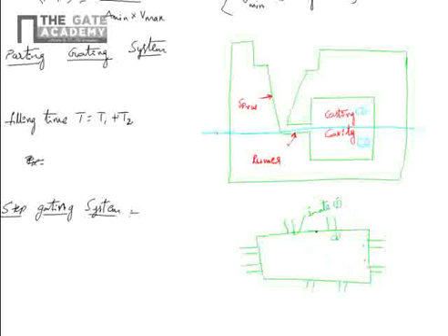So there are so many gates. If there are multiple gates, this is used for very complex, huge castings. When the casting size is huge, then we go for multiple gates instead of a single gate, for large castings, especially machine beds.